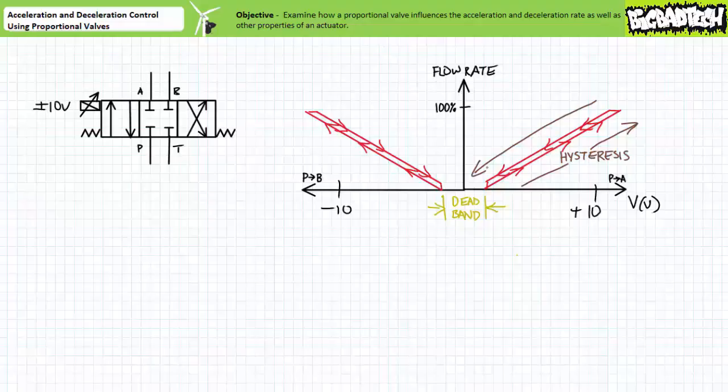diagram. Finally, because the proportional valve is inducing a restriction, quite like a regular flow control valve, we can expect a double-acting cylinder to actually extend faster than it would retract given equal applied loads. The cap end, having larger functional area, necessitates less pressure to move a given load. This means the proportional valve will experience more of a pressure differential during extension at a given applied voltage and more flow as a result.